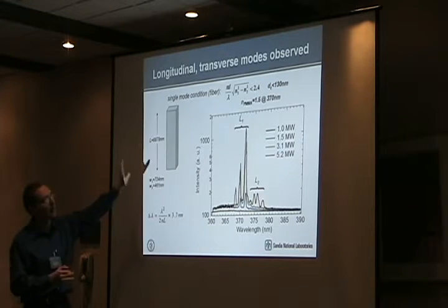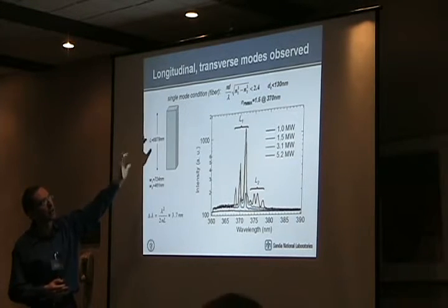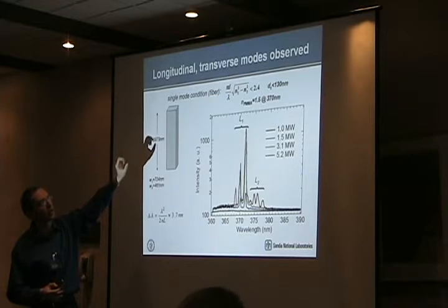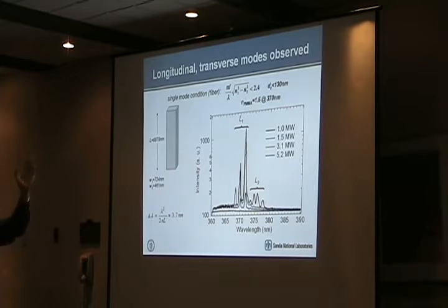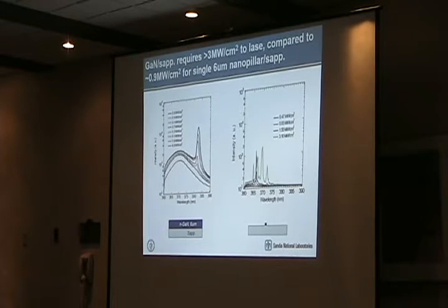But clearly the dimension here is larger than the critical dimension that you can calculate from just optical fibers, very well known. What's going to be the critical dimension to getting just a single mode? And given the index of refraction of PMMA, I'm getting 130 nanometers. We're above that, so we would expect to have transverse modes.